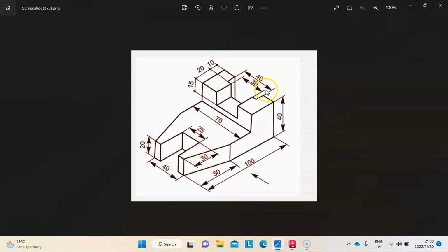We're drawing it on the right since we said this is first angle orthographic projection. So we're putting it on the right. So what do we see from this side here? We see a rectangular shape that has a 70 going that side.